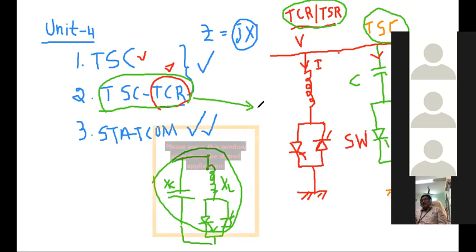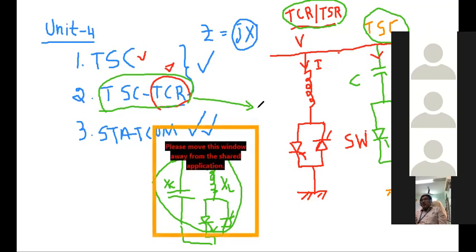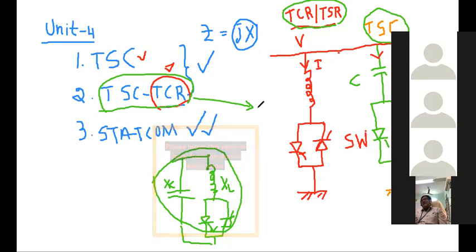You have to understand how the reactive power flows. In this case you are measuring the power factor clearly, using a power factor meter. There we know whether the power is inductive or capacitive, because the power factor meter has both leading and lagging, and at the center you will have the unity power factor. We take all the readings.